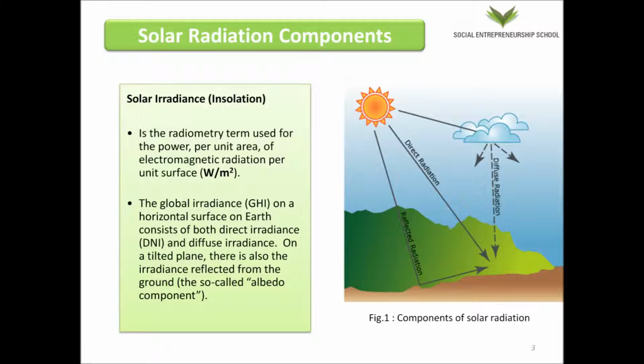Radiation scattered through clouds is called diffuse radiation. This is still capable of producing electricity in non-concentrating systems. So normal solar panels will be able to produce electricity from diffuse radiation only. You can say roughly 20% or so of the energy of the solar panel rating can still be produced with diffuse radiation. And then you can also have reflected radiation from the ground produce electricity. This may be taken into account when designing the system surroundings.